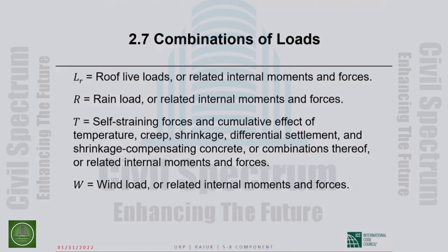If the concrete is allowed to shrink, there is no problem. There is a little bit of shortening, but that typically is not an issue. The problem is that concrete structural members, at least in cast-in-place construction, are monolithic. A beam will frame into columns or walls. So when the beam wants to shorten because of shrinkage, the columns or walls that the beam is framing into will not let it shrink. And that is a problem.